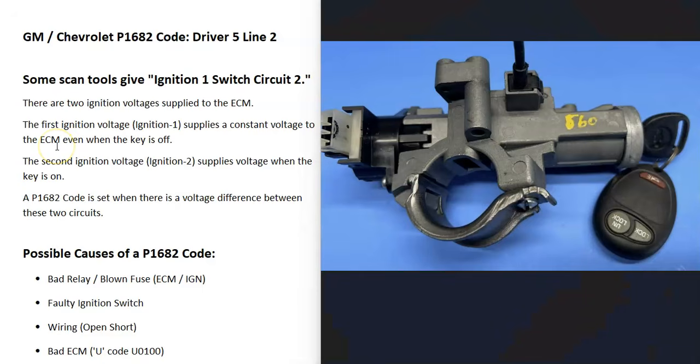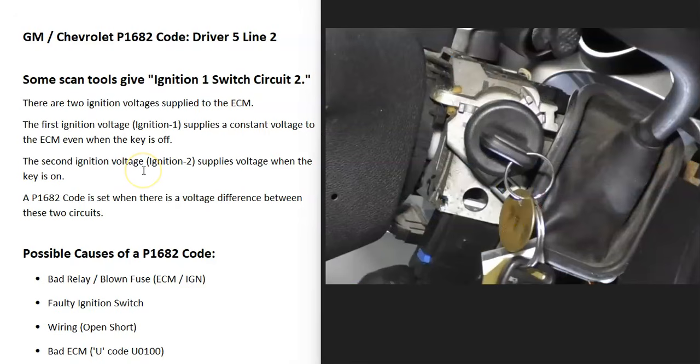The next thing that could cause this is that the ignition switch went bad and it needs to be replaced. If anything goes wrong inside that ignition switch with the contacts or the connections or anything like this, then it could cause problems and it's going to cause issues. So the next thing that could cause this is a bad ignition switch.